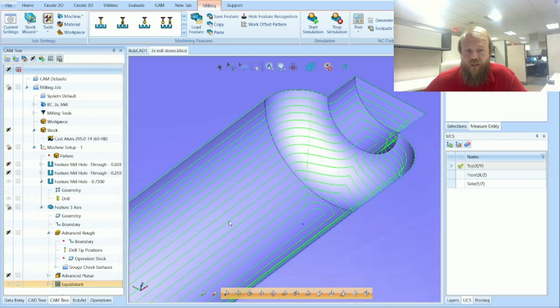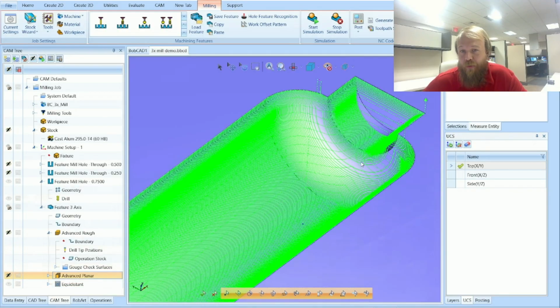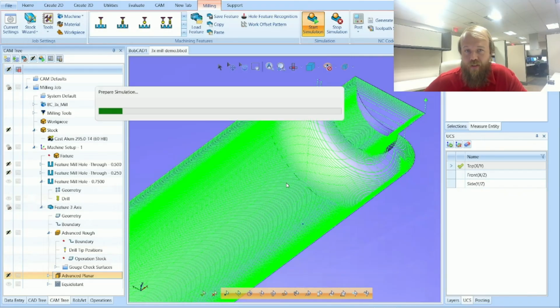So that's where the rest machining operation is best utilized, where you can simulate after the planer toolpath, go into the save stock option. So we'll look at that icon again here.